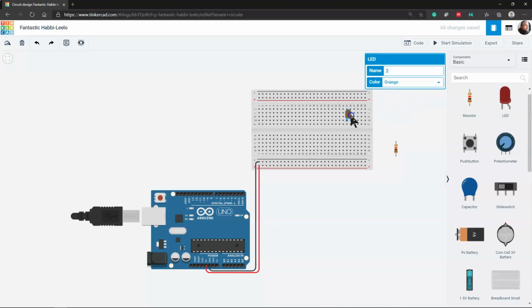So we'll go and get this into the board. And then once again here, boom. I am putting it in between two rows because then it means the anode is connected to this entire row right here and the cathode is connected to this entire row here. So the next part is to bring in the actual resistor and connect that. I don't want it connecting to both rows, so I want to click on it and rotate the component so that it's going across rows.